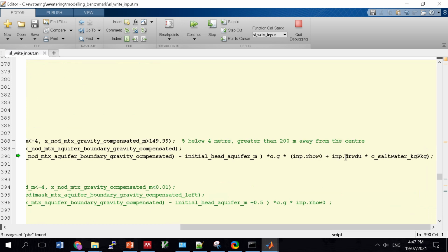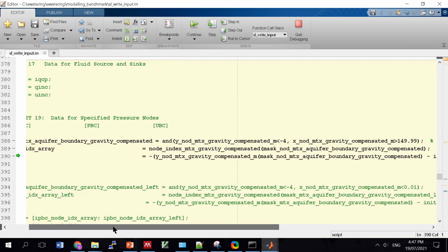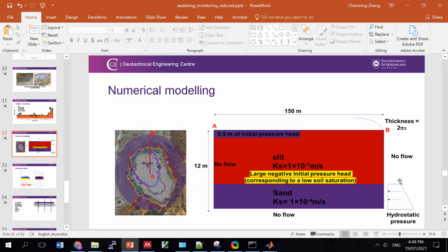This function shows how the pressure is calculated based on this trapezoid. Initially you get a small pressure and that increases, and we also add the density impact there as well. So that shows how this trapezoid is implemented, and if you want to use different elevations, you just need to change that function.